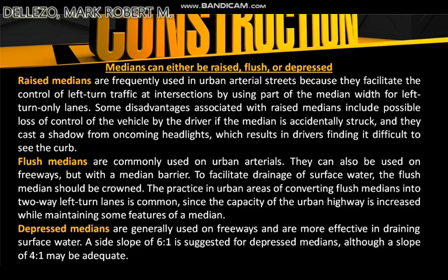To facilitate drainage of surface water, the flush median should be crowned. The practice in urban areas of converting flush medians into two-way left-turn lanes is common, since the capacity of urban highways is increased while maintaining some features of a median.